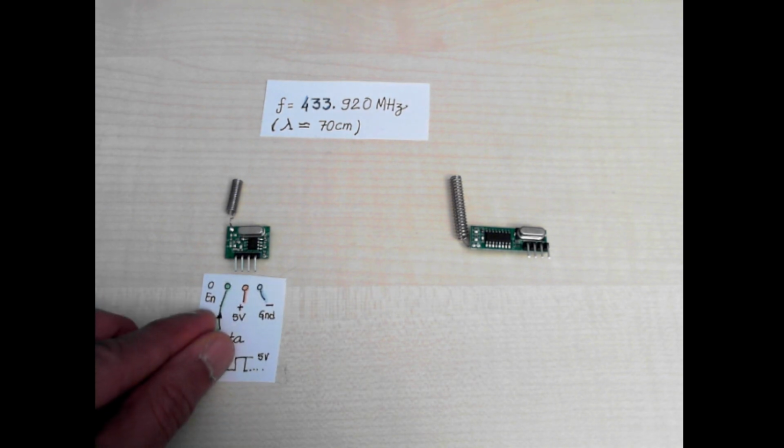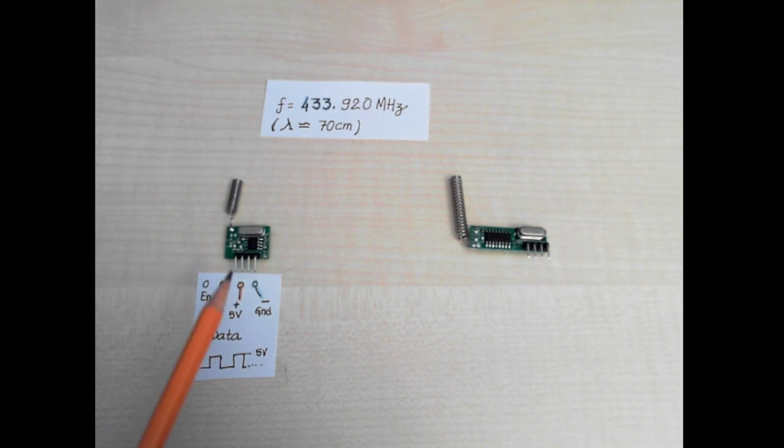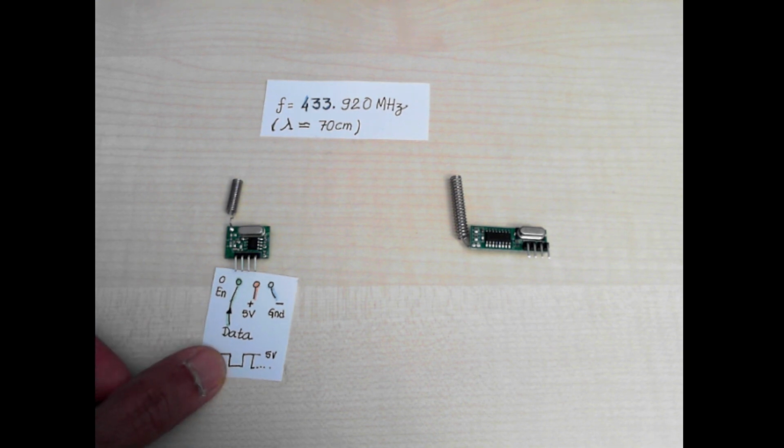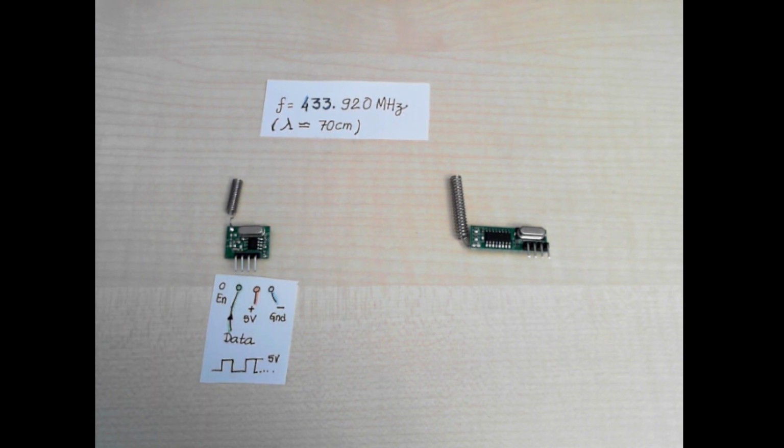The transmitter module has 4 pins, two for the power supply, the ground and the 5 volts. And then one of the pins that is here, you can provide the data input by setting it to 0 or 5 volts. The last pin, enable, is something that we are not going to use in our application.